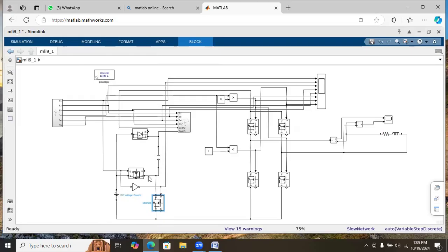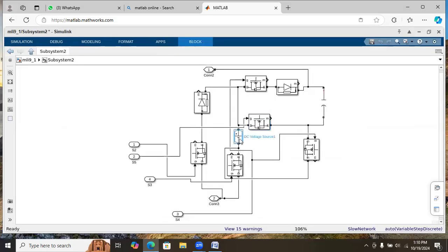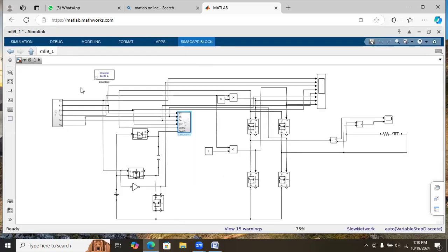And when the capacitor is discharging, this switch will be off and this switch will be on. So the capacitor will be connected in series here. The capacitor voltage gets added with the input voltage source. So 9 plus 9, 18. And here also the same thing, 9 plus 9, we will get 18. Totally 36 volt we will get as the peak voltage.